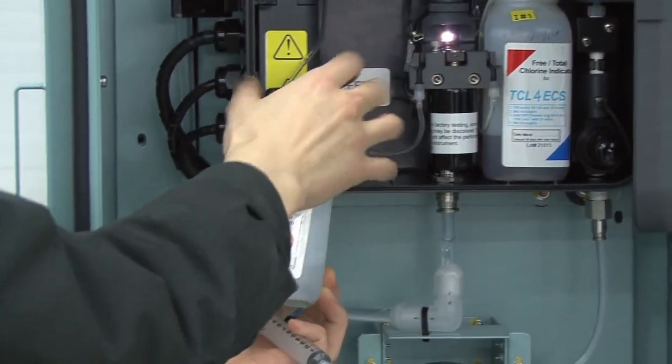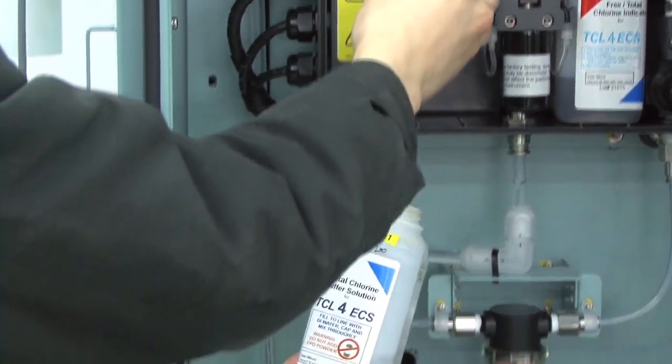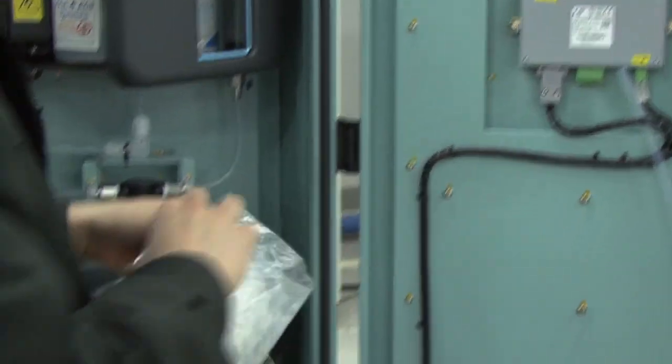Step 3. Remove reagent from CLX sensor. Clean the pipe by injecting fresh water to the pipe with flushing kit. Flushing kit is placed in TSU drawing pocket.